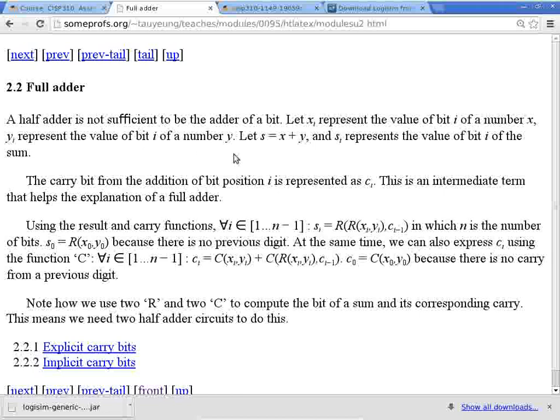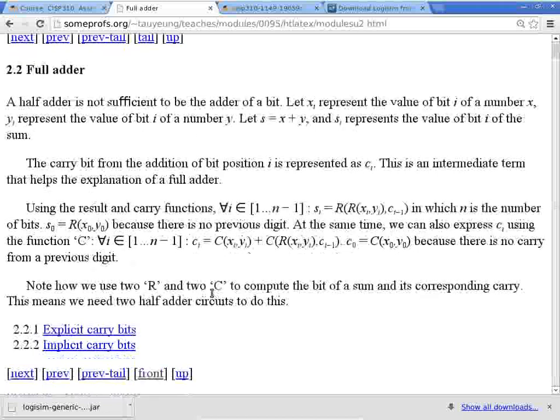A full adder is made out of 2 half adders. I use this kind of obscure way to describe stuff, but for the most part, it's really just saying that the carry flag of 1 full adder becomes the input carry of the next full adder, and so on. It's basically just saying how the carry flag is propagated.